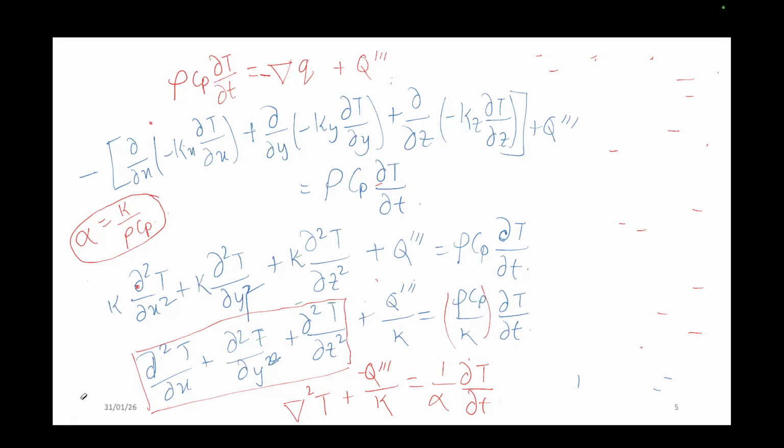In the numerator, what is there? k is there, right? So basically, it indicates, say, a solid block. In a solid block, how much heat is conducted, and the denominator indicates how much it is thermally storing this energy. Among the energy conducted into the system, how much the system is storing, that basically represents this thermal diffusivity alpha. Have you got it?